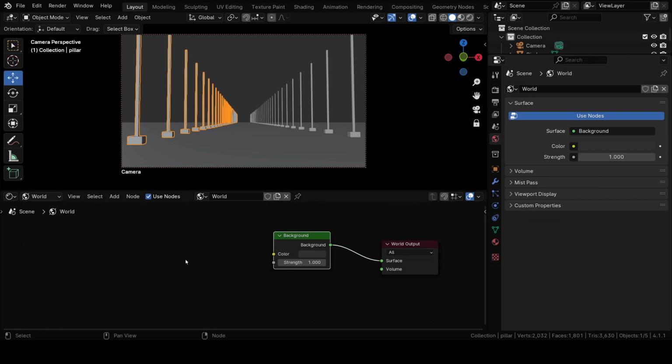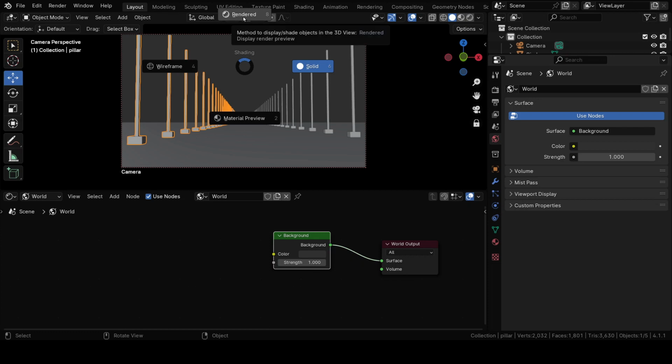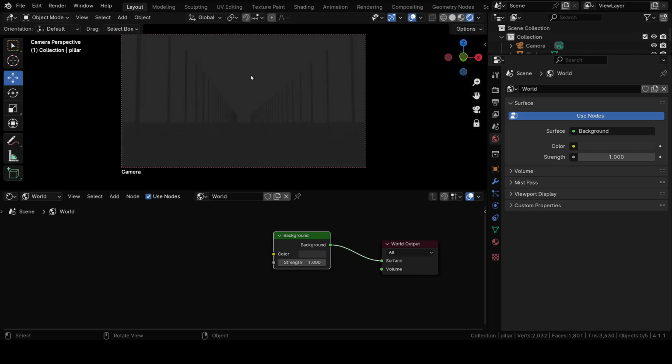So now we are going to add the sky. Instead of adding a light, I am adding the sky itself. Then, if we need, we can create a light or something, whatever we want. Now you see I am pressing Z on the keyboard in the 3D viewport, and I am choosing rendered. It is now in solid mode. I am choosing rendered. There is no light here. It is completely gray color.